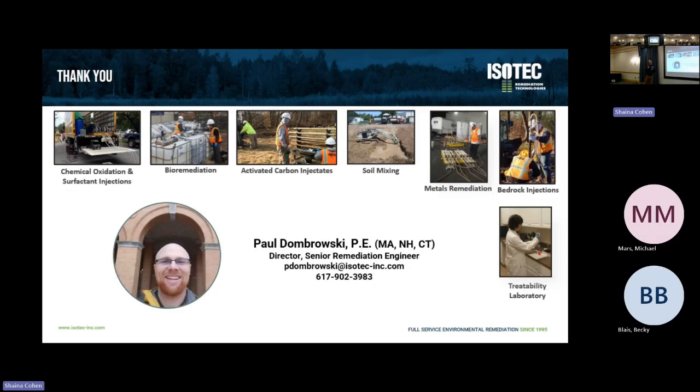But the intent of these is not to affect the hydraulic connectivity. So the wood chips and gravel, those are great because, and one of the other PhDs that I'm working with has done some hydraulic connectivity estimates of wood chip gravel mixes through column testing and the like, and you're increasing your K value by an order of magnitude maybe, which is awesome for PRB purposes.